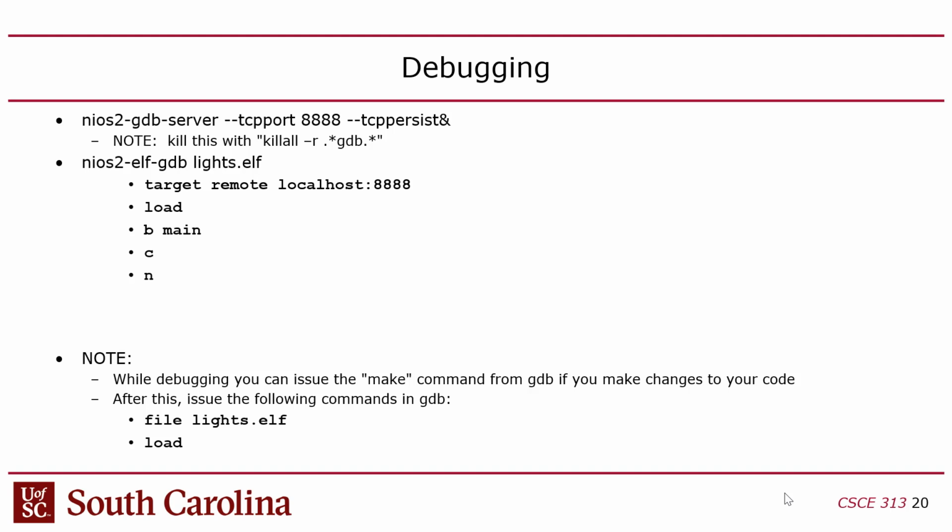Now I need them. The problem is Arduino doesn't have one. Like if you use the Arduino IDE, no debugging. So you have to use print debugging. The problem is that if you use print debugging, you go over the JTAG UART, and if you print too much too fast, it'll overrun the buffer, because the JTAG UART is very low bandwidth, right? JTAG is like 5 megabits, right? But remember, that's the baud rate.